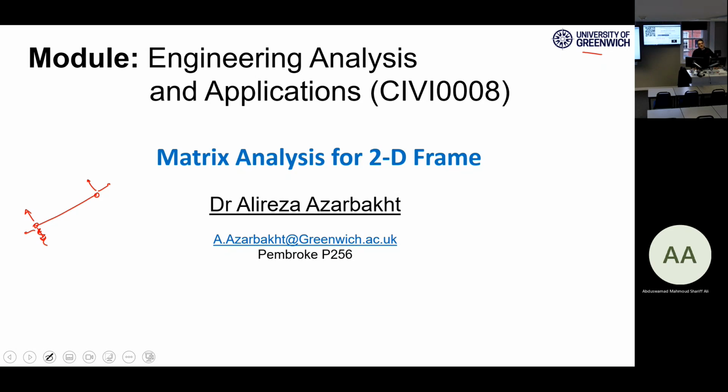So, for example, if you had a big structure with different elements with different joints, it would be easy and enough just to count your joints and multiply your joints by 2 to come up with the degrees of freedom, right? If you know the degrees of freedom, you know the structural stiffness matrix dimension. If you have, for example, a structure with 5 joints, 5 nodes, it means that 5 multiplied by 2 is 10. You will work with a 10 by 10 matrix, right? When you're going through these structures, just count the number of joints, multiply by 2, you will figure out the dimension of your matrix. So if you go back through the examples we've gone through, when you have joints, just count them, multiply by 2.